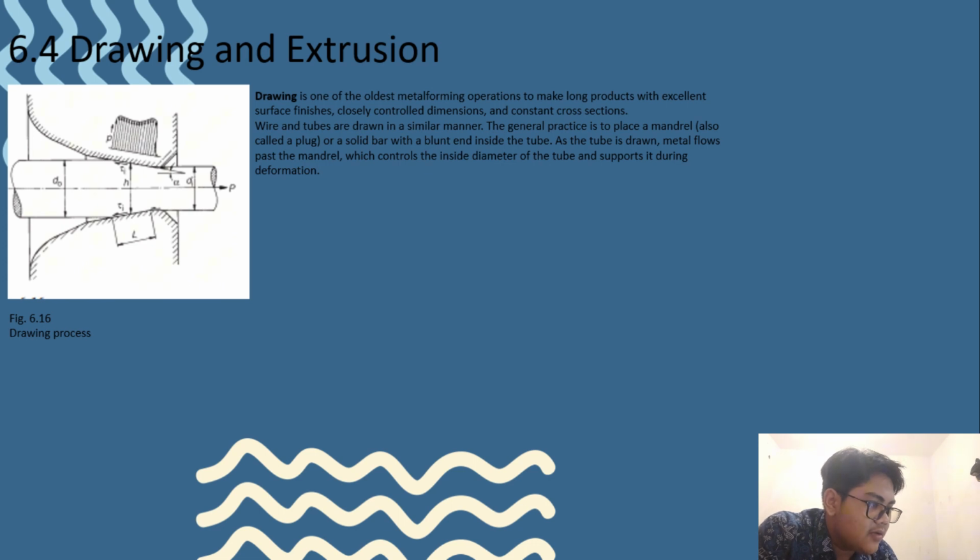Then last we got cold extrusion. In this process, metal is squeezed or squirted through a hole in a die. Low melting point and relatively ductile metals such as aluminum, tin and lead are easily extruded. The most commonly cold extruded metals are, in order of increasing processing difficulty, aluminum and aluminum alloys, copper alloys, low and medium carbon steel, modified carbon steel, low alloy steels and stainless steels. Special glass lubricants are used for the cold extrusion of certain steels.